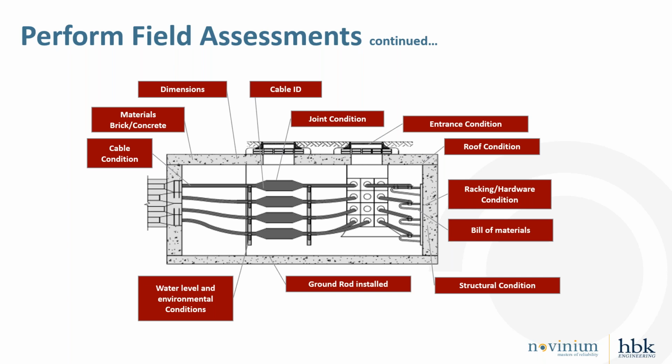If present, a secondary bus or secondary connections would be checked for blown limiters and fuses, which would then be noted for replacement. Transformers, switches, molded vacuum interrupters, and equipment such as that would also be checked, as well as any communications infrastructure and equipment, fiber optic cables, and slack coils.